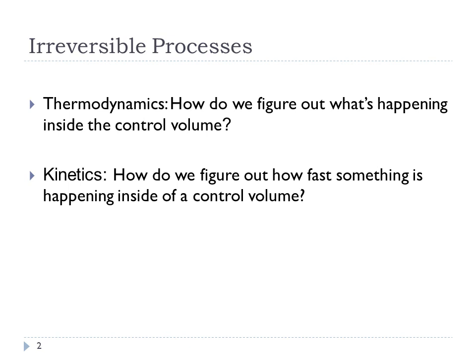In this one, we're going to ask the question: if we need a certain amount of heat transferred in a certain amount of time, and we have a certain temperature gradient, what's the area of the heat exchanger that we need to get that much flux for a given gradient? That's what I'm calling kinetics here. It also goes by the term non-equilibrium thermodynamics.